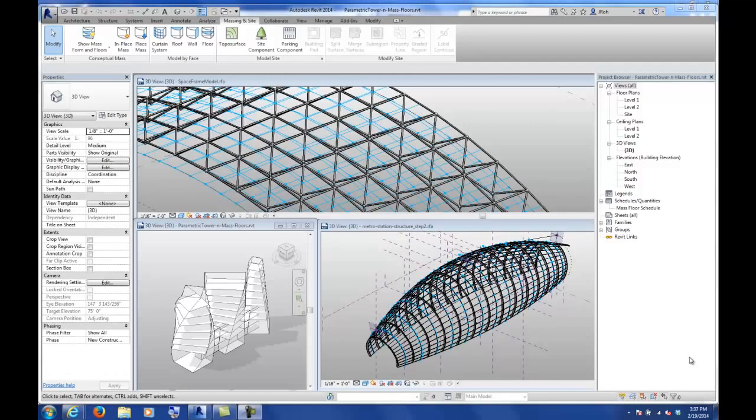I also wanted to cover getting into some of the tectonic details in the project environment. We touched base a little bit on parametric families last time. It was real basic. We made that rectangle and never really went back to it. So I want to use that parametric rectangle for a reveal and some sweeps on a wall system. And then since you've got a presentation coming up, I was also going to show some very basic ways of representing your work out of Revit.